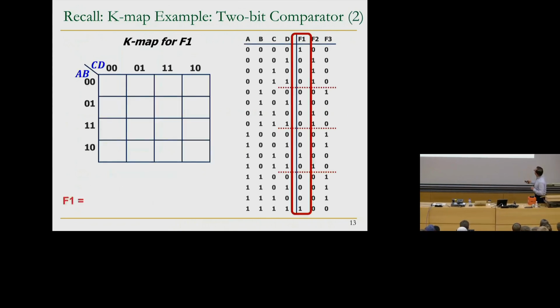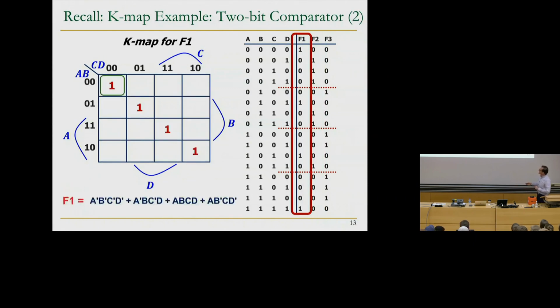We first started with the truth table. The truth table was correct, and we decided this is F1. And F1, we cannot minimize. The largest circle you can have here that combines multiple ones is essentially only 1, which means the minterm sum-of-products form is the minimal form here, because you cannot combine a single one with another one. Makes sense, right? You remember all of this.